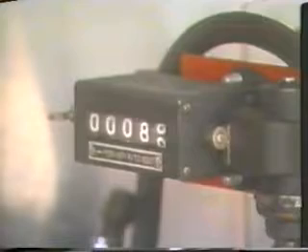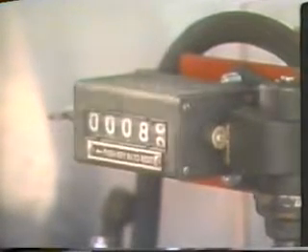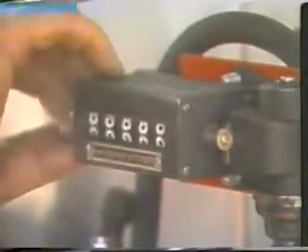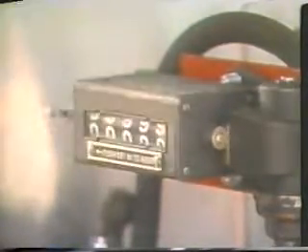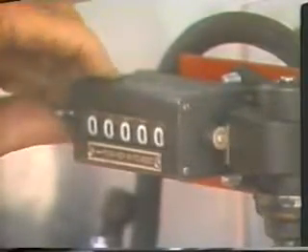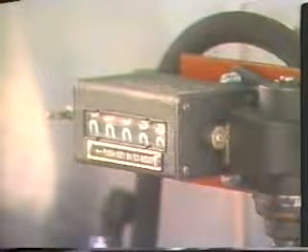The feet counter is attached to the shaft of the counter wheel either directly or via a cable, similar to an automobile speedometer cable. It is geared so that each revolution of the counter wheel counts off 2 feet on the counter. The counter has a key which allows the wireline specialist to zero the counter before lowering the tools in the well. The weight indicator tells the wireline specialist the weight or tensional force that is being pulled on the wireline.